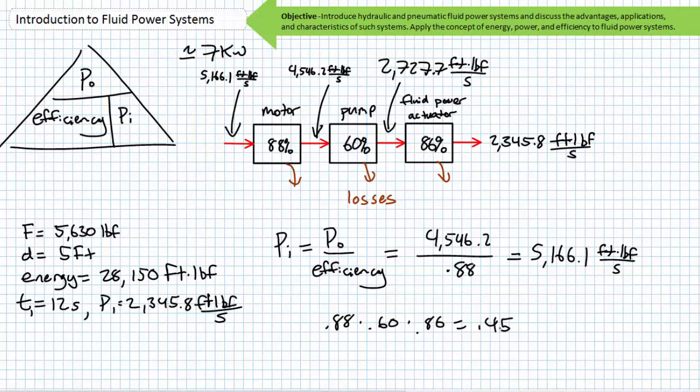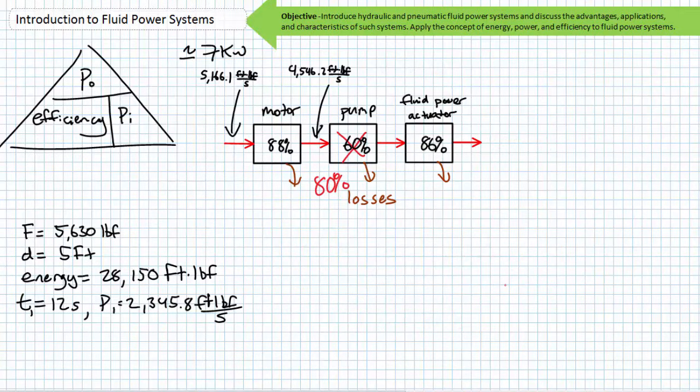Given the pump is the weak link in our system, consider not an expensive upgrade of this system, but rather a troubleshooting and maintenance procedure that identifies and corrects a misalignment or a damaged coupling between the motor and pump shaft, such that this stage now converts 80% of the rotational mechanical power to fluid power. Let's work through this example problem the opposite direction, from input to output, operating under the assumption that the motor still consumes approximately 7 kilowatts of electrical power.